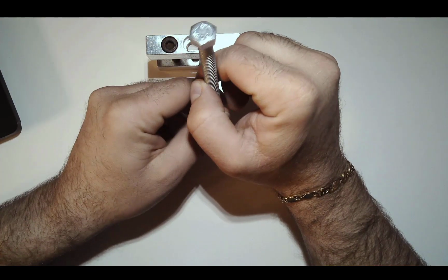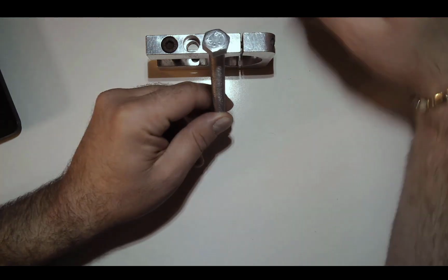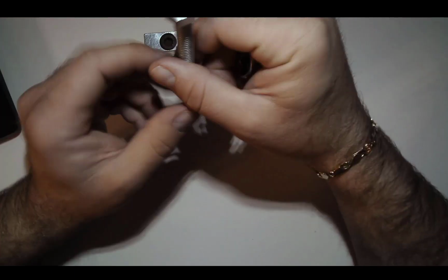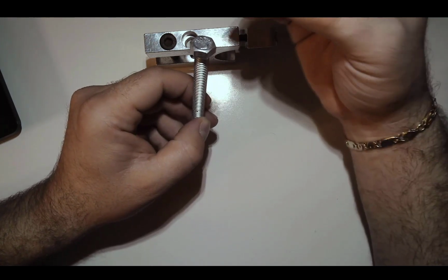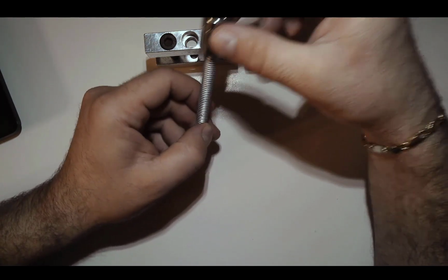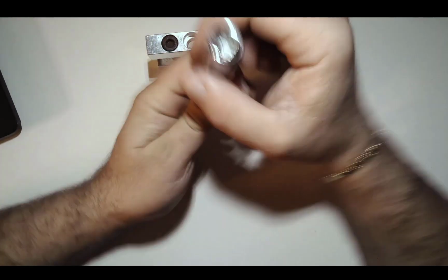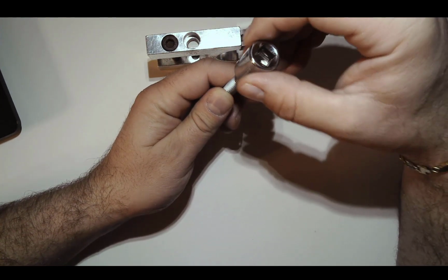I could in fact create a counterbore for a hex head cap screw if I wanted the hex head to be below the surface of whatever I was fastening, but I would have to also think about how I am going to tighten up this cap screw. Typically we might use a socket, because a box end wrench wouldn't be able to fit into a counterbore. So I would have to make this counterbore so that it allows for the wall thickness of a socket, so I can actually tighten the fastener up within the counterbore.